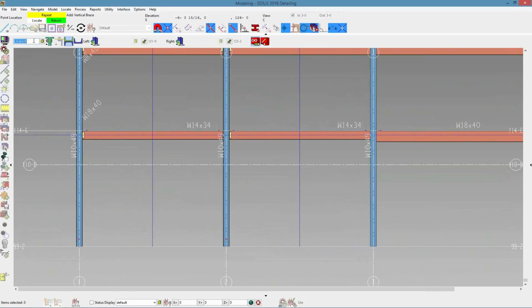Once again, you have your section size. So if we're adding in HSS 4x4 by quarter, as soon as you tab out, just like your member edit window, the member add options bar will update to reflect the options that go along with that section size. So you do have your long leg side, long leg outstanding, your double material, your angle leg, your left end connection, left end elevation, right end connection, right end elevation, continuous add, and your launch member edit. So right now I do have the continuous add mode turned on.